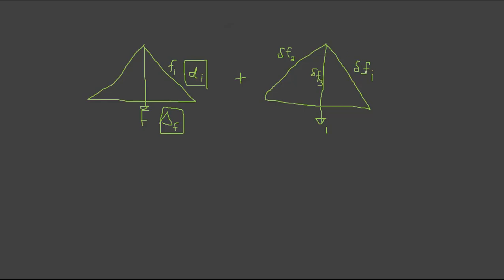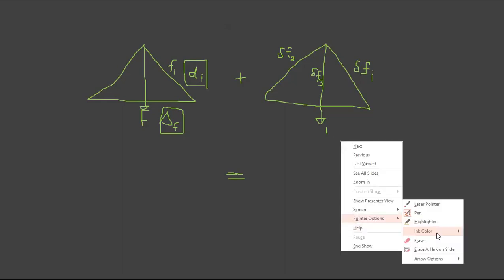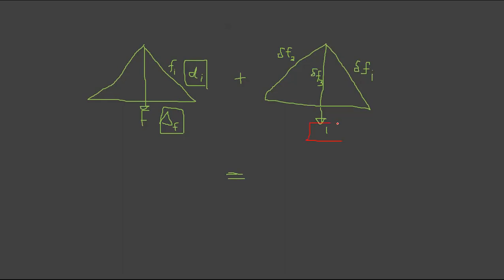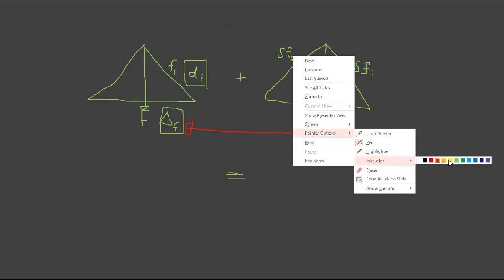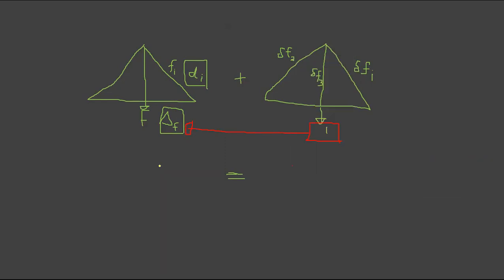So what you have to do is you multiply this delta force. So your equation is given by whatever you virtually applied multiplied by the original displacement, right? You virtually increase the load, and multiplied by the original displacement in the structure, right? Not the displacement in that particular structure, displacement in the original structure at that point, right?